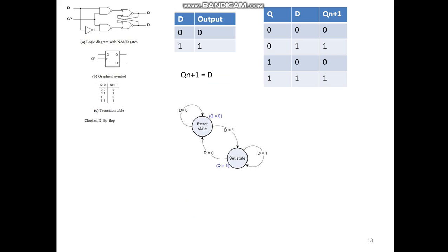That means delay. If you give a clock pulse, one clock pulse, then only the 0 will be connected with the output. So you require time for execution, this process will be one clock pulse. This is the delay, that one clock pulse. If you want a 5 clock pulse delay, you have to use 5 D flip flops in a series manner. You can get the 5 clock pulses delay. This is mostly used in the buffer circuit.